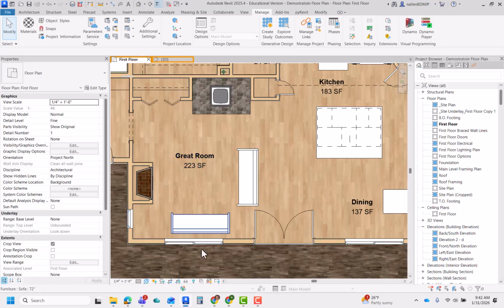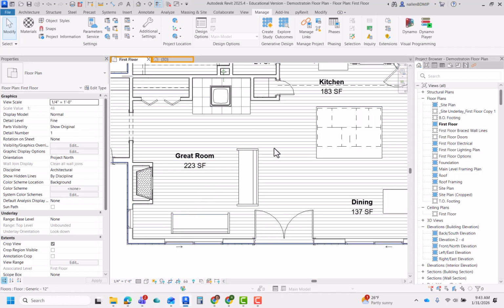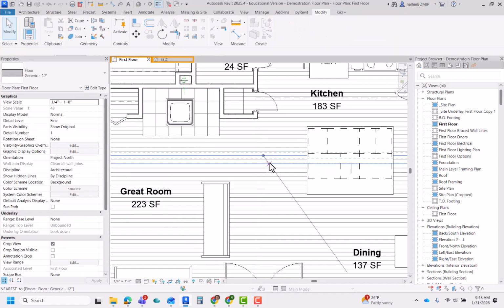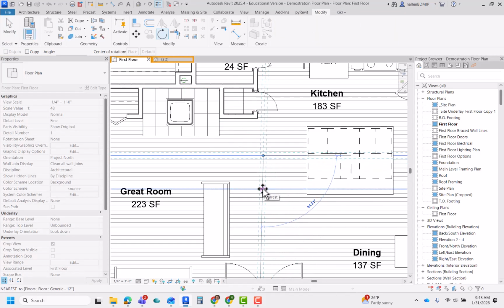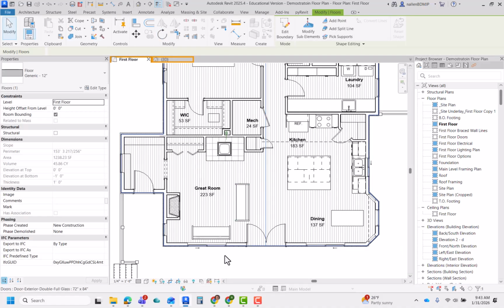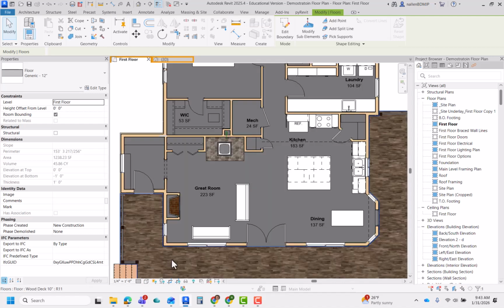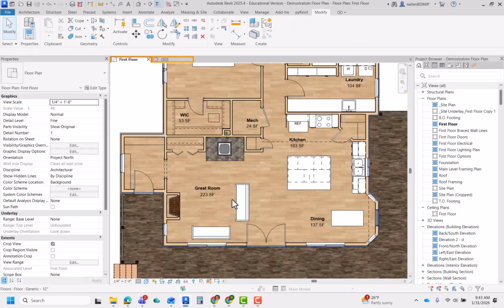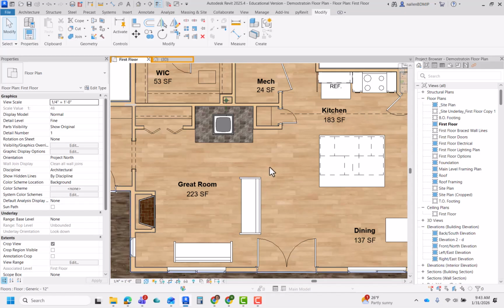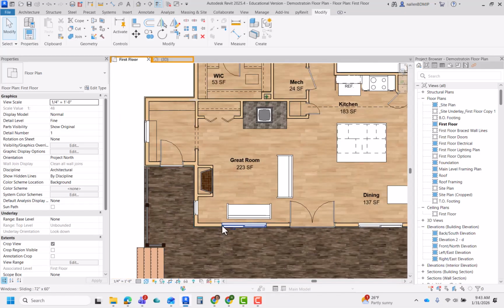I don't know why, but I'm going to fix it. You can fix your orientation by going back to hidden line, and then you'll hit tab to select one of these lines and then rotate it. Okay, and if I rotate it, I'll type in 90. Okay, ironically, this is now running up and down, and when I go to textures, it should be running left and right. Yep, and now it's running left and right. So just a strange thing. I don't know why it's not following the same direction, but at least there's another way that you have to rotate material inside your project.